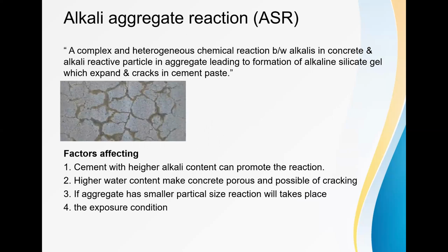Then let's see what we mean by the alkali aggregate reaction, that we are going to call ASR. It is a complex and heterogeneous chemical reaction between the alkalis in the concrete and alkali reactive particles in aggregate, leading to the formation of alkali silicate gel, which expands and causes cracks in the cement paste.